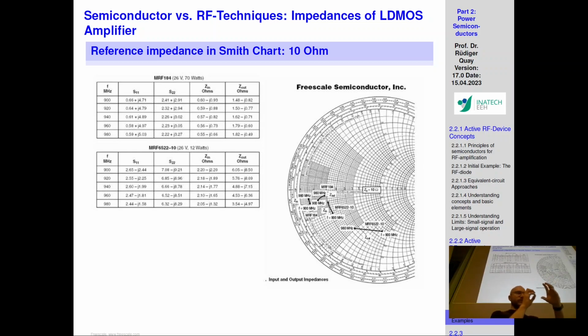In order to drive the power into the antenna, the power amplifier load has to be matched to the input of the antenna, a complex conjugate matching. And even before that, the power that is driven into your amplifier also has to be matched to its input. So your amplifier has to be accepting that. It's a two-port device.